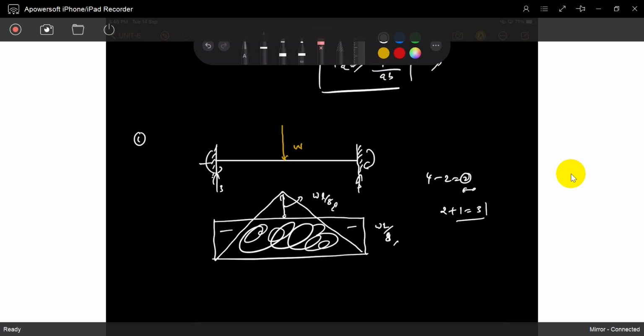Sir, here it is exactly all similar, sir. So that's why I will do this. If it is loading like this, the fixed joint gets the maximum moment. So if the load is increasing, the first hinge is formed at this location because it gets the maximum bending moment. So that's why it reaches the MP state. First it forms the MP, so first the hinge is formed at this location.